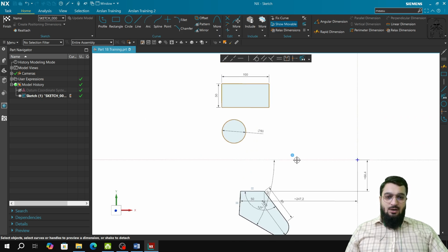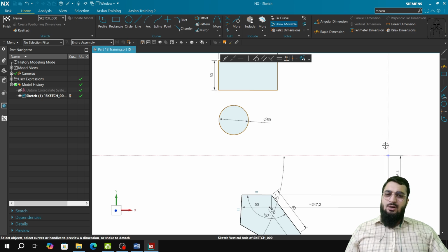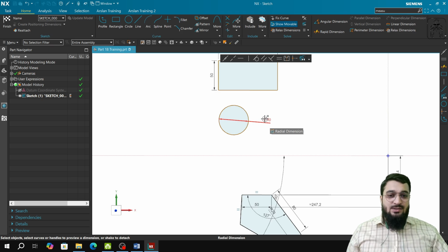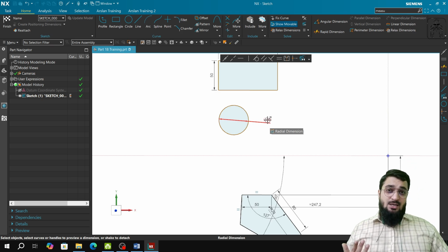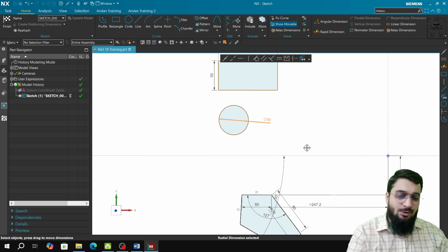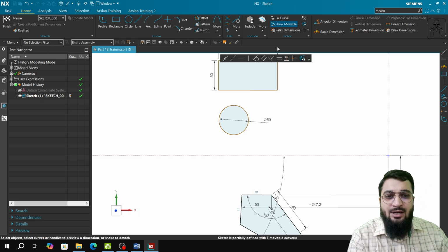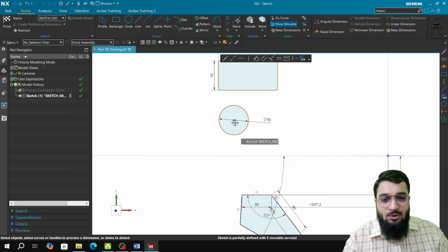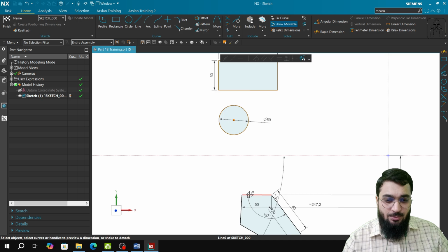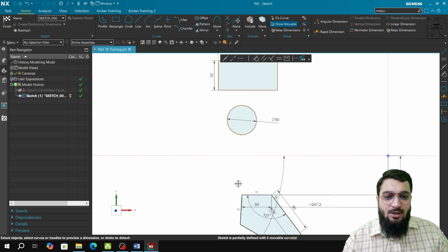Now coming to the arc that we created. In a circle, there is only one thing that needs to be defined, that is the radius. And the radius can be defined either by geometry or by dimensions. For example, this is 50. We can constrain it by using this arc center and taking the origin, or we can take any other thing. For example, I want to define it like this point and this point should be vertical with each other.